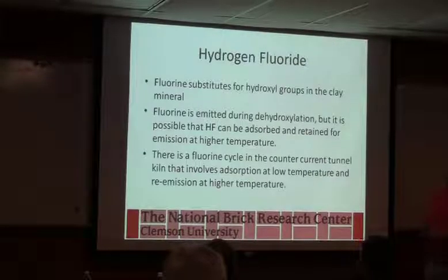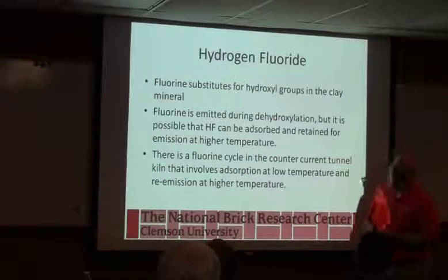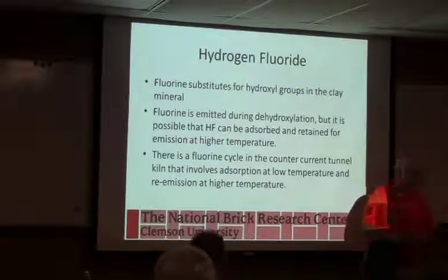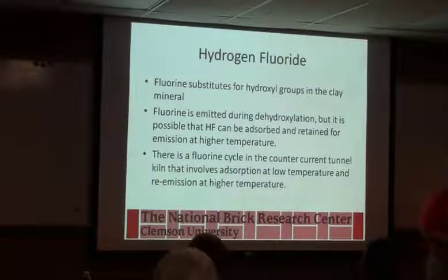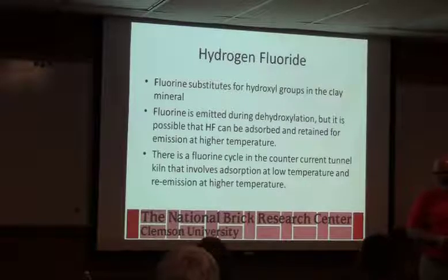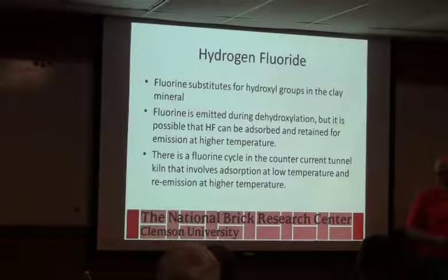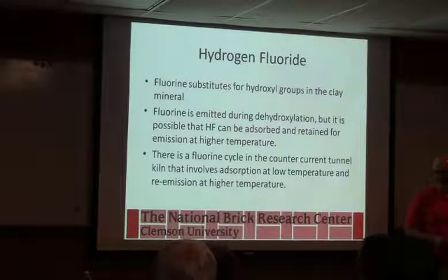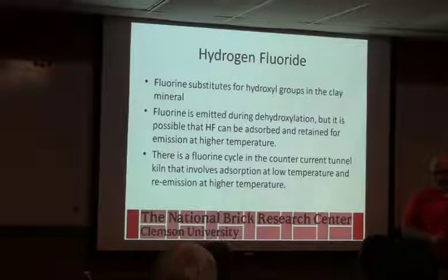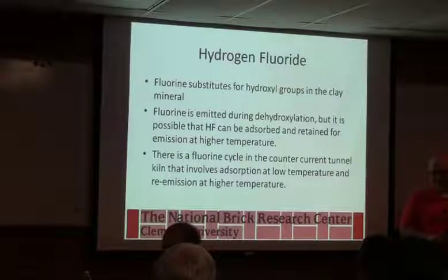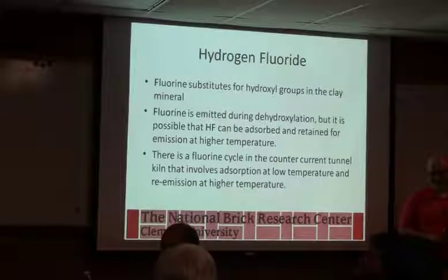Fluorine, the levels, the thing I always look at when I go in a brick plant, I look at the glass in the control room over the kiln. Is it real frosted? If it's real frosted, there's some fluorine in the air. So it's not sulfur, that's fluorine? That's fluorine that does that. We change ours out every year and a half, 2 years. Yeah. We always assume, I always call it sulfur burn, because it was like it's into the glass.